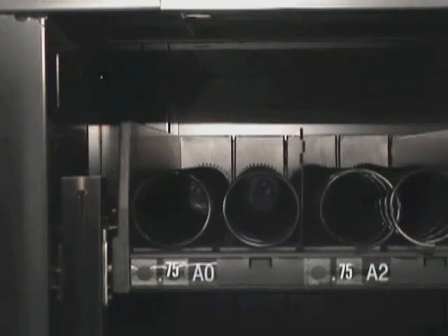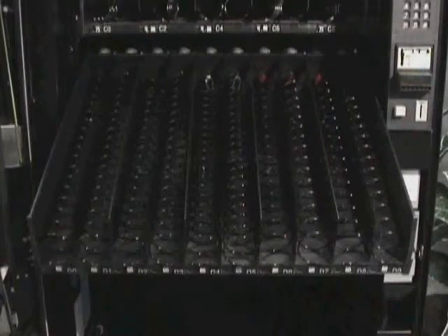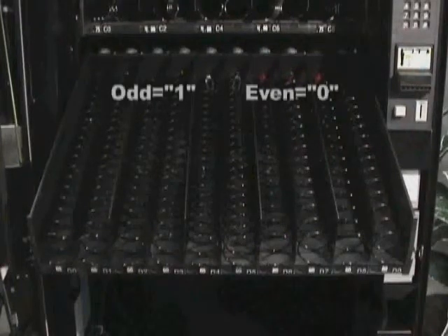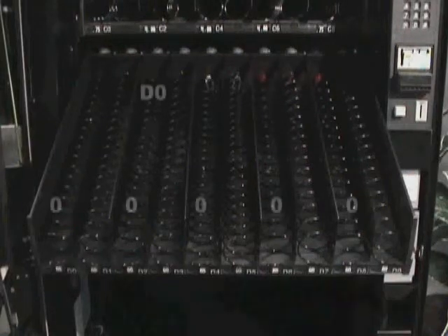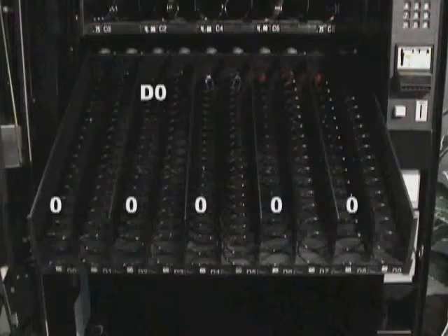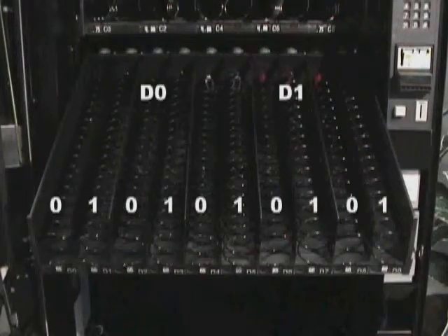In order for any motor to run, both column and row signals are needed. Candy trays use 2 row lines for control. The motors are organized in terms of odd and even. The even-numbered row is connected to all even-numbered selections. For example, row D0 is connected to D0, D2, D4, D6, and D8. Odd-numbered rows are connected to odd selections. So D1 is connected to D1, D3, D5, D7, and D9.